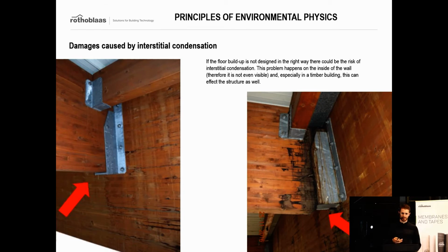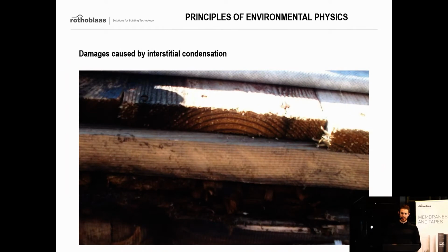This is, for example, an example of what I was previously talking about. In this floor buildup, some designers chose the wrong membranes, and therefore we had condensation on the inside.